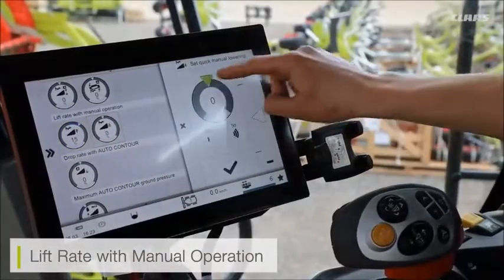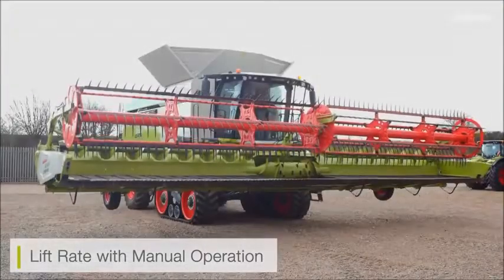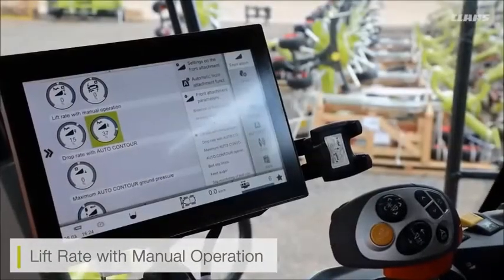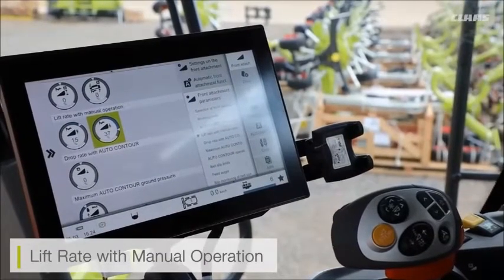And also for the lower setting, I can increase that sensitivity. So if I increase that sensitivity right up, when I lower it, I have a quicker reaction for lowering my cutter bar. Making sure that if I have the sensitivity too high, I need to be wary that I'm not going to start digging my cutter bar into the ground when overpressing my main cutter bar button.